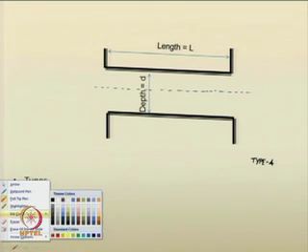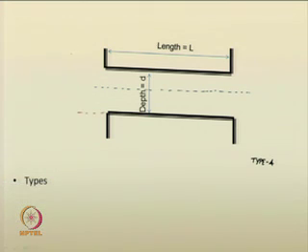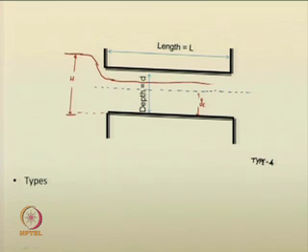So, if this is the headwater depth h, depth of the culvert d, this is the critical flow depth inside the culvert, you may have a situation where the flow will go like this inside the culvert, and it maintains this same depth in the exit also. So, YT. So, this is the type 4 flow.